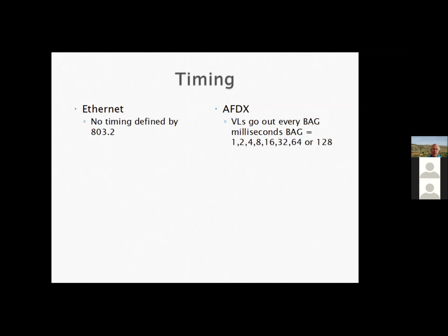Now, obviously, these are the things I'm going to play with: how frequently the data goes and how much data has to go out with that frequency. And if I multiply the amount of data times the frequency, that tells me the percentage of the bus that I'm going to take up. And when I do that to all of the devices on the bus, that tells me the total throughput of the bus.